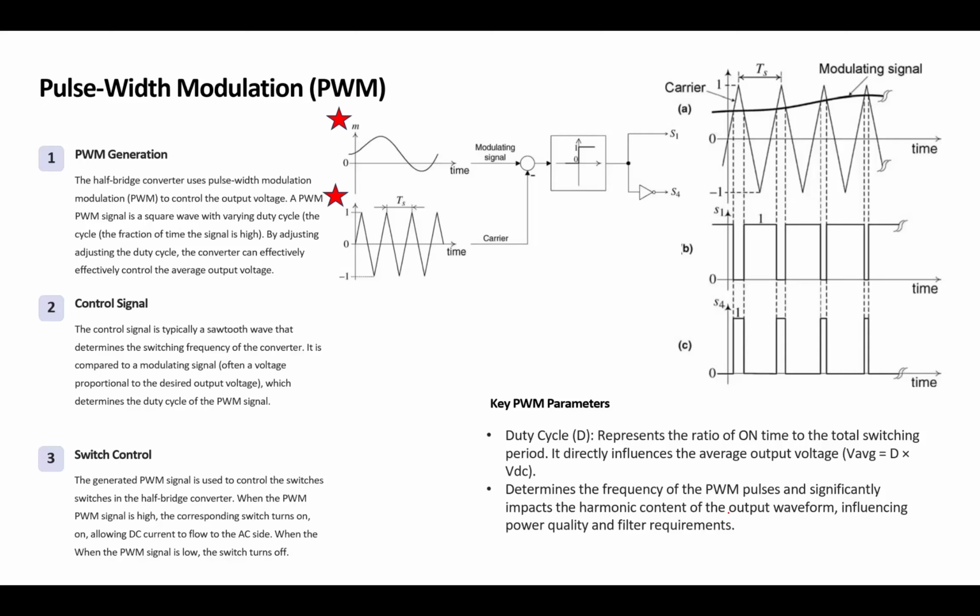This is our hand, basically. This is our will, that S function. The rest of it, we don't have any control over it. This is a characteristic of the system. The S is our leverage. Now, how we define S, how we control S, there are tons of switching methodologies and techniques. You could search on that. The most popular one that we are going to use in the inverter, and we're only going to focus on that, is PWM, which stands for pulse width modulation.